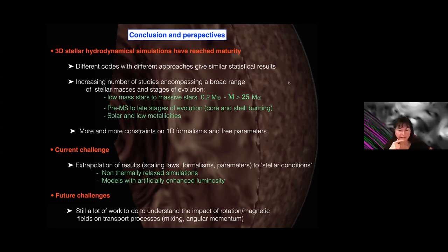It makes sense. I would say that it's more or less embedded in the scheme. It all depends. Some codes, for example, if you rely on implicit large eddy simulation, are really relying on the scheme. So you rely on your truncation errors to define your numerical viscosity.